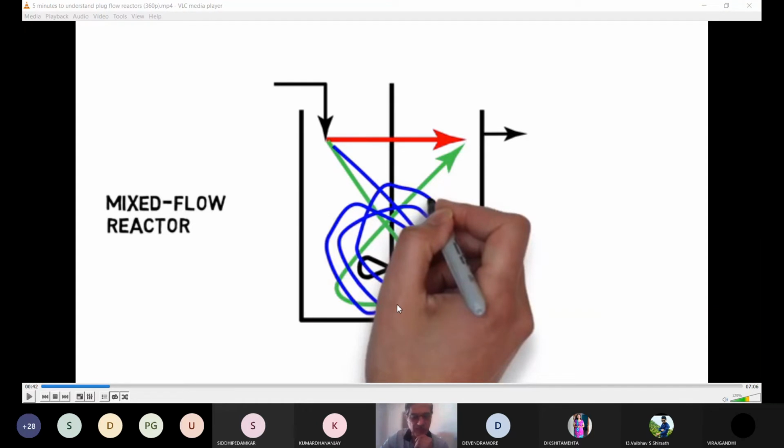तो इसीलिए constant ही maintain करते हैं, because कम ज़्यादा होगा तो flow rate कम ज़्यादा होगा, right? If you don't maintain the constant volume, तो flow rate also will keep changing, because hydrostatic head भी होता है उसका, right? अगर यहाँ पर मेरा level कम हो गया तो यहाँ से flow rate भी नहीं होगा. Suppose I have an outlet from here और मेरा level नीचे आ गया तो outlet ही नहीं आएगा. And that is why we keep an outlet at the same level as inlet और slightly below that or above that, so that we can maintain a constant level in the reactor.